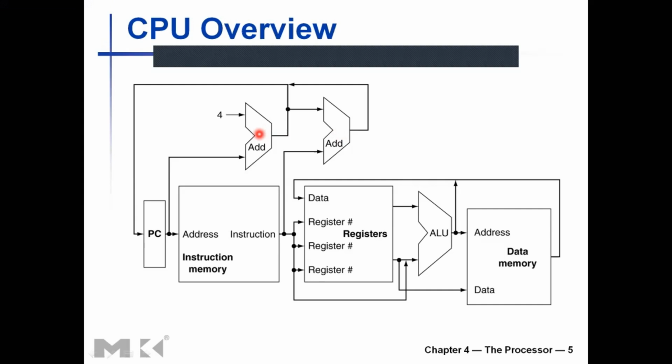So here, when you're adding an offset to that, you need to make sure that you add the offset as a byte address, not a word address. Otherwise, you will not be able to get to the correct instruction, or you will not be able to make the correct jump. So you need to add the immediate value as a byte address, not a word address. So keep that in mind. We will see that come into play in future as we discuss this in detail. Right. So that is the instruction fetch mechanism. Any question on that?